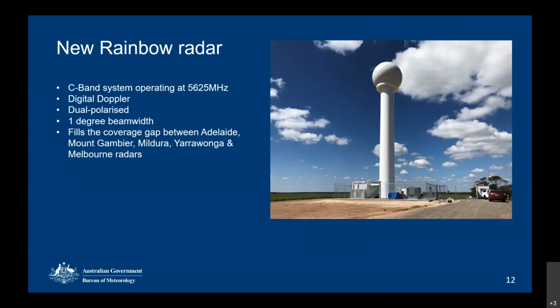It's a C-band radar. We operate our radars in two different frequency bands, C-band and S-band. C-band operates in the frequency spectrum of 5600 to 5650 megahertz, and our S-band radars operate in the 2700 to 2900 megahertz. S-band radars are a lower frequency radar. They generally have a bit more punching power in monsoonal areas, so they will punch through higher density weather. However, their definition is not quite as good as a C-band radar, but with modern digital processing, they're pretty much both the same now.